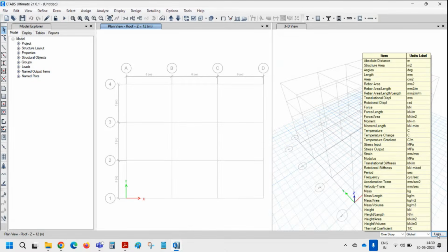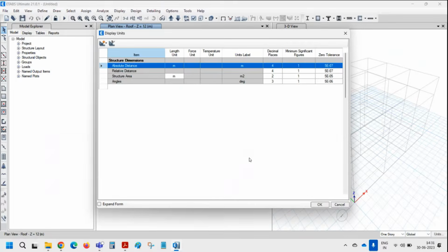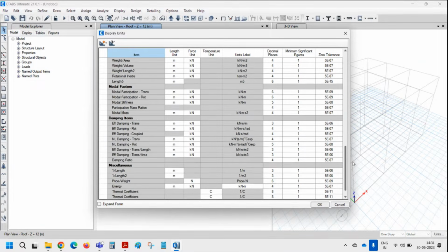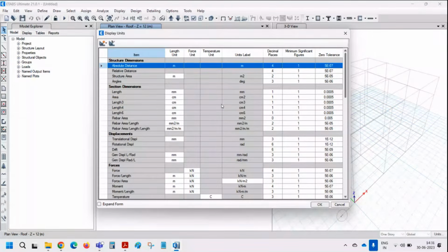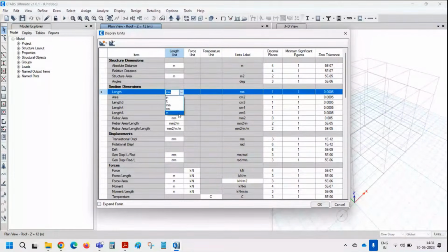And then lastly, you have the units. You have access to quickly set to defaults of that particular system you're working in, or you can set it to consistent units, or you can modify individual items to any unit. For example, length is in one unit; you can change this to meters, inches, feet, etc. So it goes for all items.